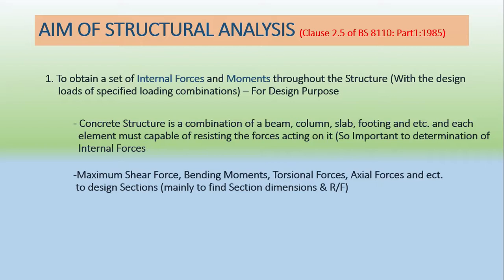If you have to design a beam, you have to calculate the internal forces, not the external forces, such as shear forces, bending moments, and axial forces. According to the values of those forces, you design the amount of reinforcement that we should provide, and also the section dimensions. So these are the main structural analysis aims.